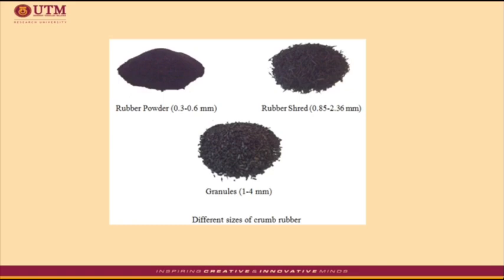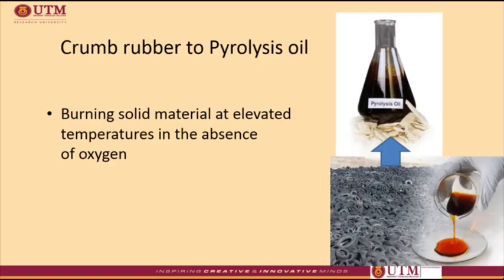On the other hand, the solid form of material can also be converted into oil for further application through pyrolysis. This process converts solid material at elevated temperature into oil in the absence of oxygen. This is a good option to reduce solid waste material in landfill and recycle the materials for other applications, specifically waste tires. So through the wet process, instead of using fine rubber powder or granules in the asphalt binder, the pyrolysis oil also can be used for the modification.